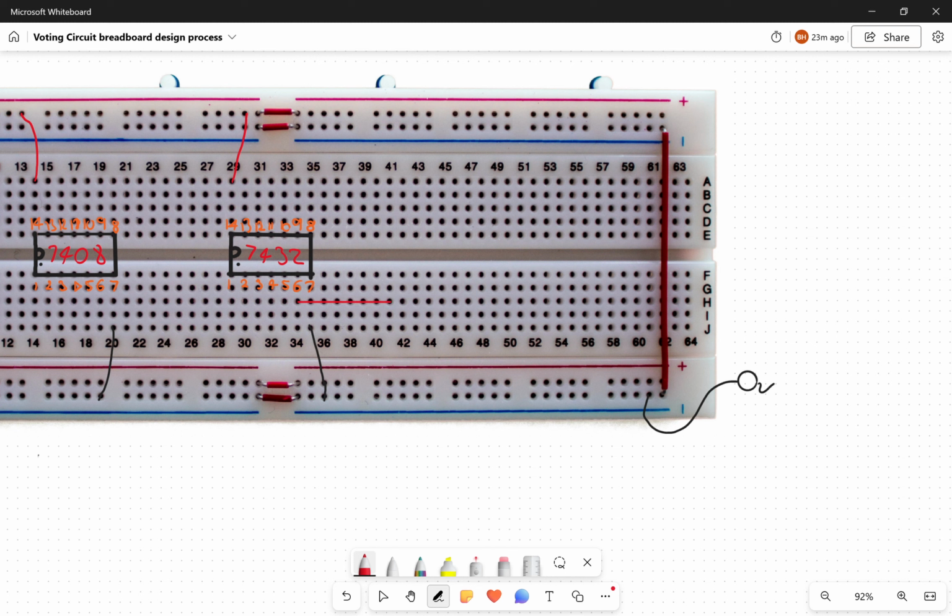And we're going to go up. I'm going to try and make it as neat as possible so it's easy for everyone to follow. Up, out and across all the way over here. And then what we're going to do is sketch in our LED, or light emitting diode, across here. Now again, we're bridging the gap between top and bottom of the breadboard, and then we are going to go down to ground via a current limiting resistor of roughly about 180 to 200 ohms, doesn't really matter which one's which.